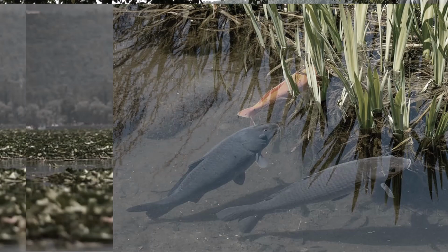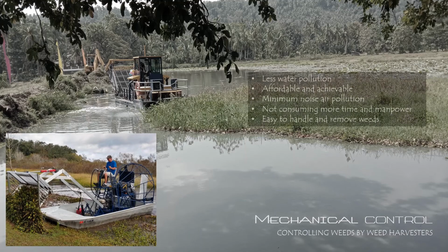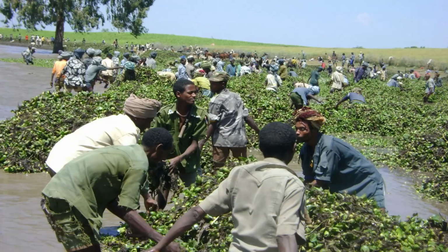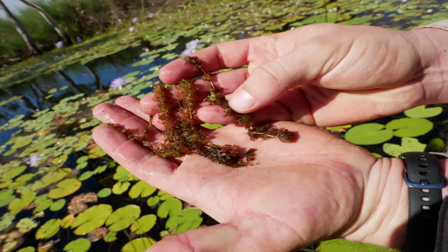Now let's turn towards the mechanical aquatic weed controlling methods, where any group of weeds is removed with machine power or any other tool. The advantages of mechanical methods start with immediate results. It's non-selective and hardly creates any conditions for ecological shifts in aquatic flora species. Mechanical methods also often reduce the immense nutrient loads of eutrophic water bodies, indirectly controlling future weed species populations. There are several methods of mechanical removal, like cutting, chaining, water weed cutters and harvesters, dredging, mowing, netting, barriers, burning, fire heat treatment, and checking weed seeds.